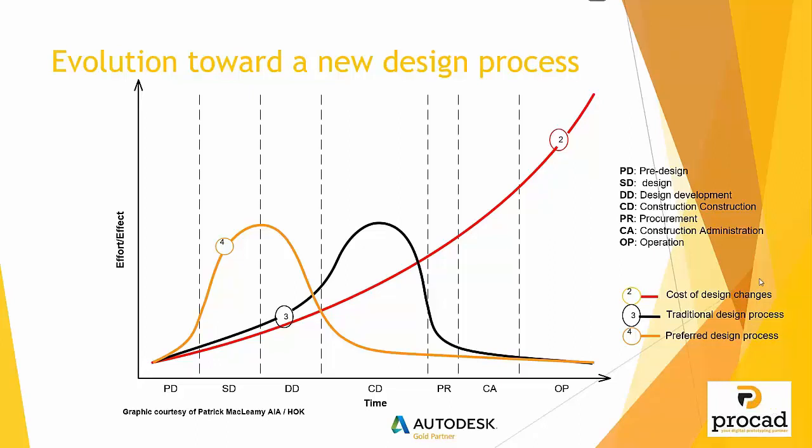But within a BIM process, because it's a lot more of a connected process, you're able to impact the change, I suppose, at a more efficient rate throughout the process. So if guys are on site, you'll have foreseen certain issues in a BIM process, using things like clash detection, which we'll cover in further webinars. Being able to foresee things like that will minimise loss of labour costs and material costs on site by having to undo work as well.